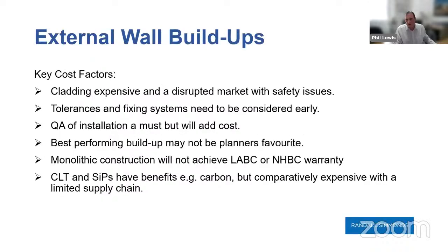Key cost factors. A few things that I'm sure we've seen when building, particularly with residential apartments, but also with commercial schemes, is that at the moment cladding is expensive and a disrupted market because of fire safety, etc. That may settle down, but cladding is an element that we all need to focus on early doors in order to make it as commercially lean as possible.